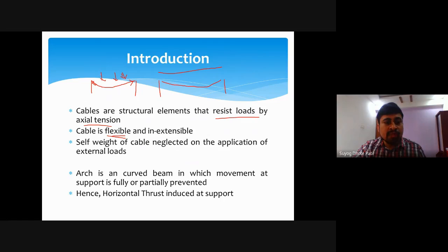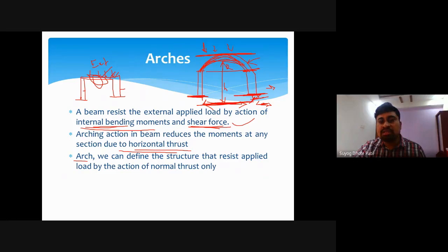Again, after application of force, this force will try to push the cable in the downward direction. This is fixed at the support, this is fixed at the support. So ultimately, after application of this load, the nature of this cable will be tensile. No picture of compression is there. Whereas in the case of arches, which are an inversion of the cable, there will be only compression, no tension.